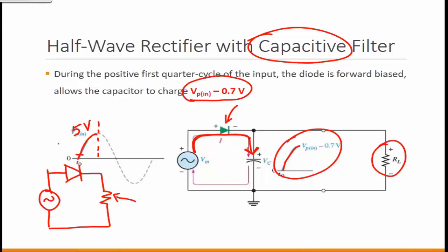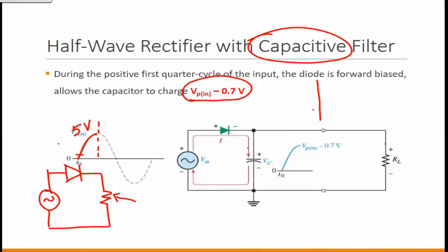So again, I'm going to state a couple of things on what we want, but what actually happens depending upon the rectifier. Let's say that capacitor is already holding that 4.3. Remember that what we are looking for is something like a straight line, correct? Because in our application, we are looking for a DC voltage.